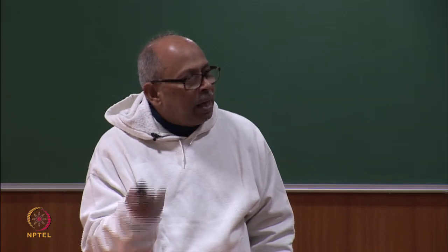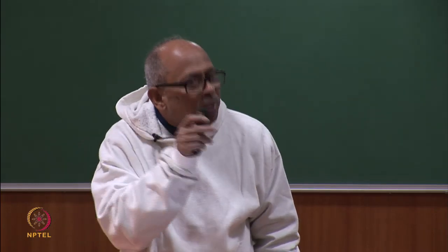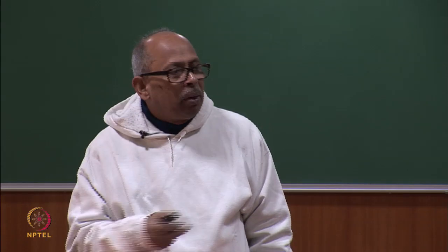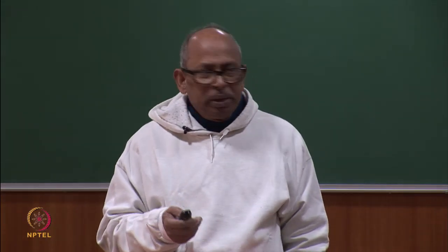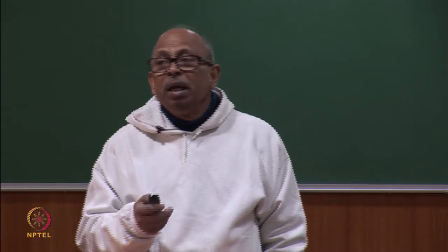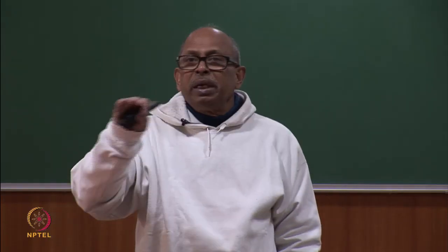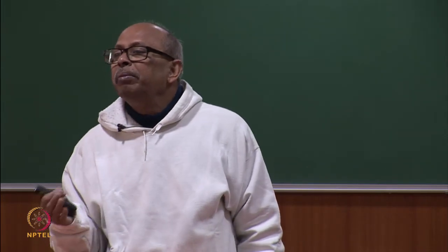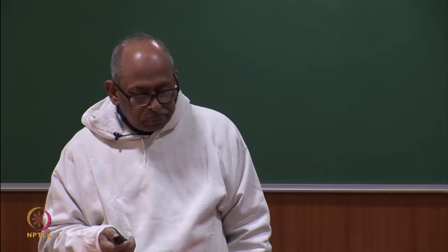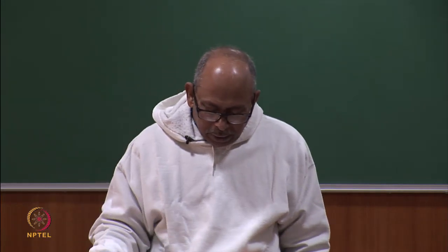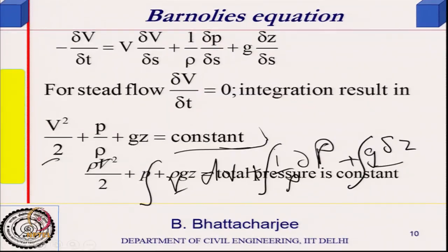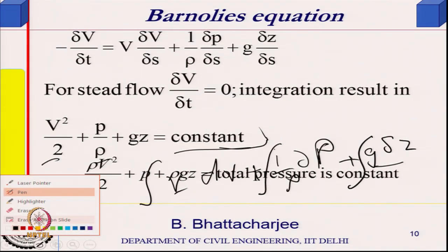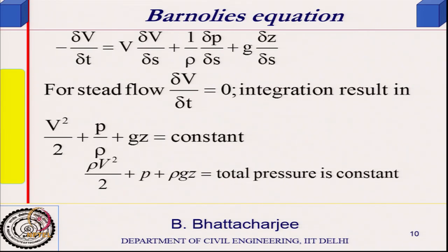So, in our fire case also we can assume that the stream flow is occurring at the top as well as the bottom, and we can apply Bernoulli's equation, and it is steady, because we are assuming the fully developed fire is going on; we are not taking into account a time variant scenario. So, total pressure is constant, you can write it in this manner.